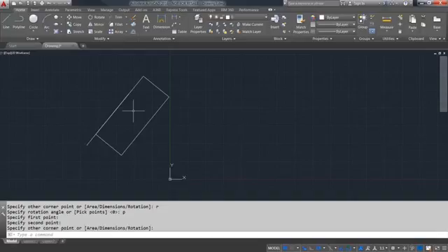If you have a version of the CUIX file from 2014, for example, which still has the classic user interface, and I'm assuming they're talking about the classic workspace here, you can drag that in with the customize user interface. And there is an article on that. Bryce, do you want to maybe put that article into the questions section so everybody can see it? That'd be great. Put a link to that.